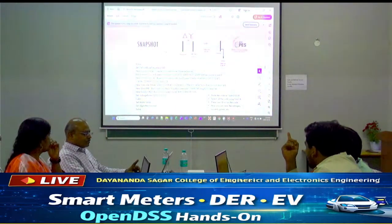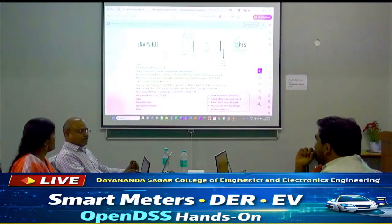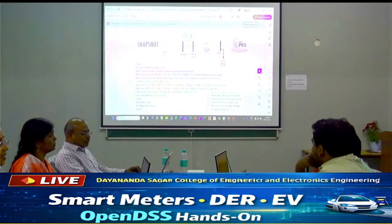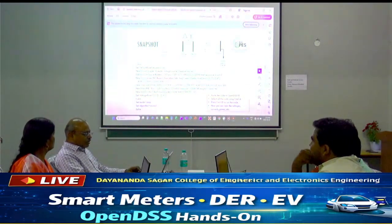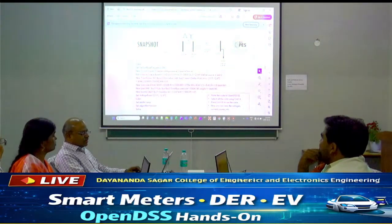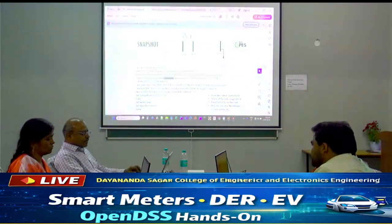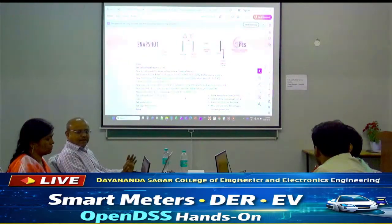If I remove the transformer, it shows it's not solved, because you have to connect it. If you want to remove the transformer and connect these two lines, then for this line 1, its bus 1 you have to give as the source bus. So you connect this one to the source bus, then the circuit will be complete. Otherwise the circuit is open. So, is this clear?